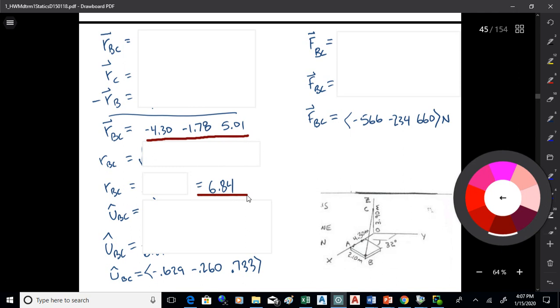See, this is actually a length in meters here. So to make the magnitude, you take the Cartesian vector, make it a unit vector, and multiply it by the force in newtons. That way the resulting vector will have a magnitude of 900. You want to get the length of the rope out of the force vector. You don't want that in there. You just want a unit vector when you do the force.